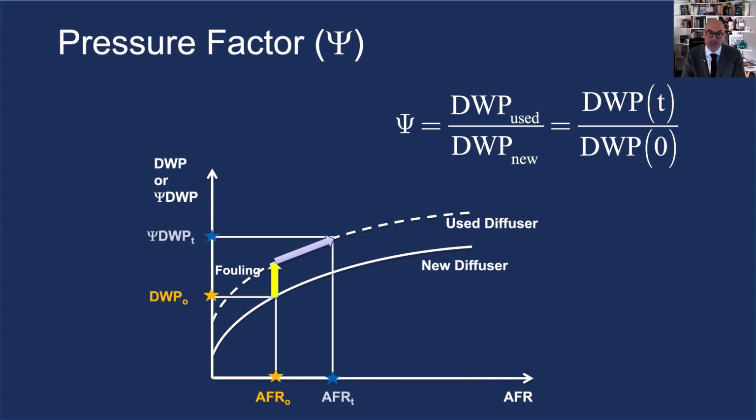So this is the effective pressure that I need to front and to overcome to get the bubbles out. So when I do the design, I don't just have to inflate the pressure requirement by the yellow extent, but by the red extent, thinking that in the future, the diffusers will have that pressure drop. And the blower needs to overcome that pressure.